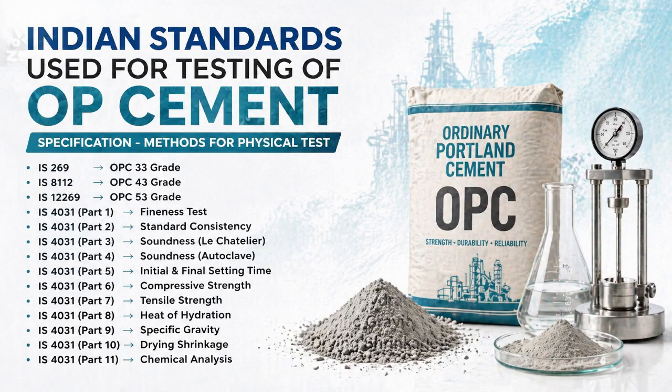Then the IS 4031 series, here I have given the details from part 1 to part 11. So this series covers all physical and chemical testing methods such as fineness, consistency, soundness, setting time, and compressive strength. It also includes tests for tensile strength, heat of hydration, specific gravity, and drying shrinkage. Together, these standards ensure the cement's quality, strength, durability, and overall performance in construction.